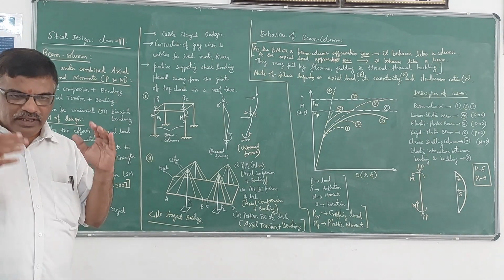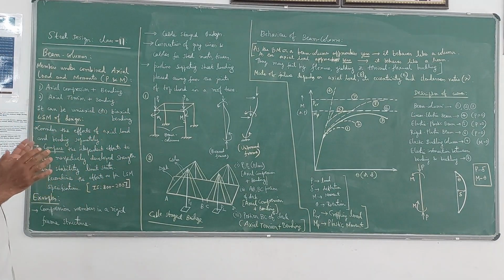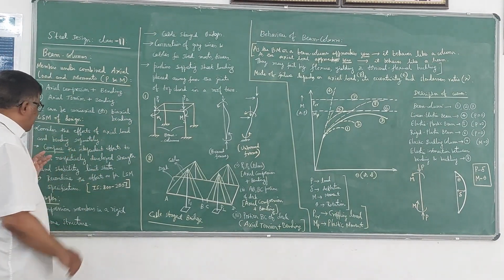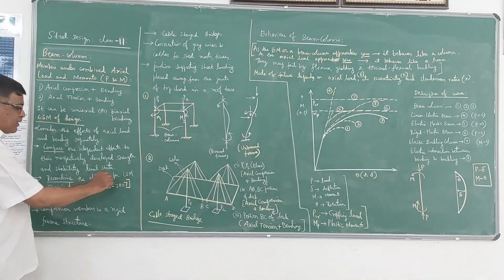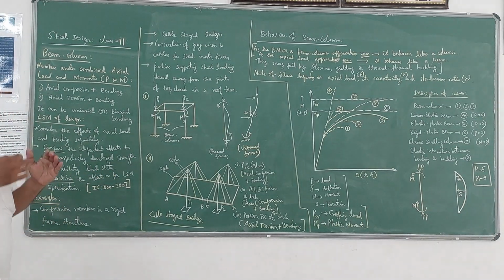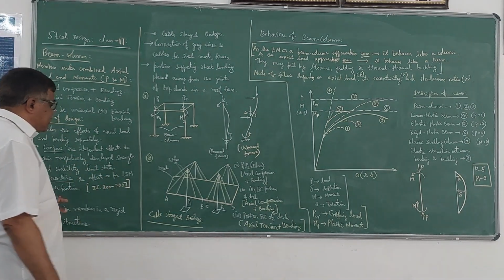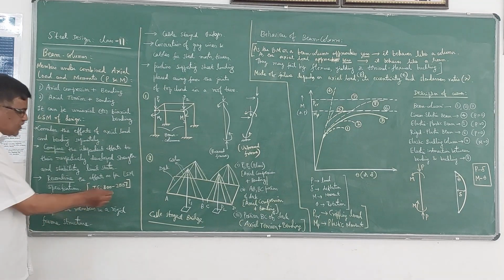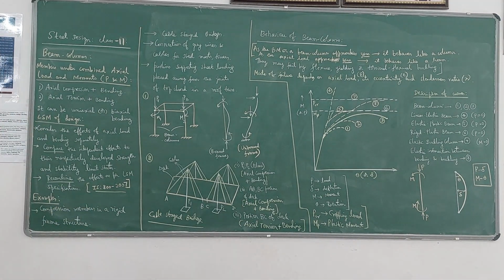Whether the beam behavior is satisfied and column behavior is satisfied, then we have to recombine the effects of both beams and columns as per the limit state method specifications available in the IS 800 2007 steel code. So these are the steps.